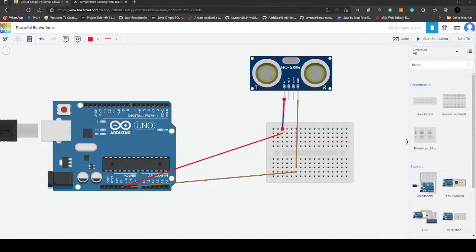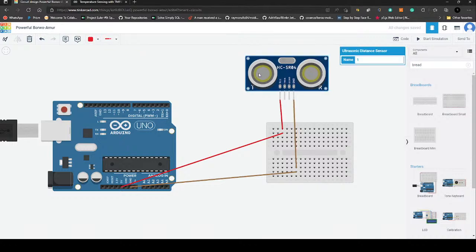Now, how does the ultrasonic sensor work, whether in IoT or the original ultrasonic which is used in ships and all? We know that ultrasonic sends a sound wave or any form of wave which reflects back, and we calculate the time taken by the wave to come back.